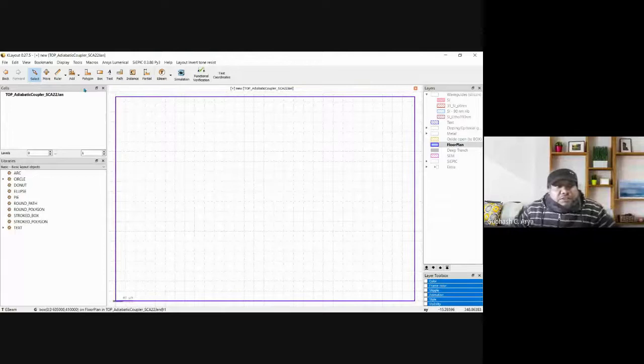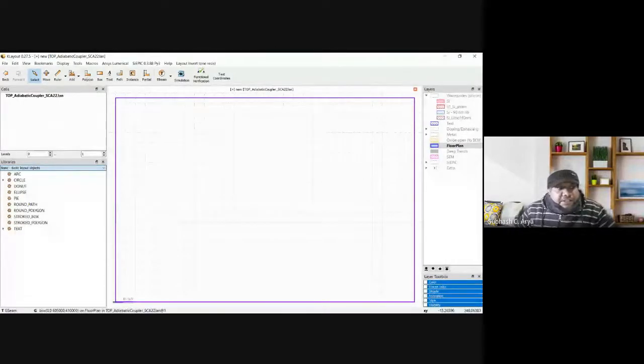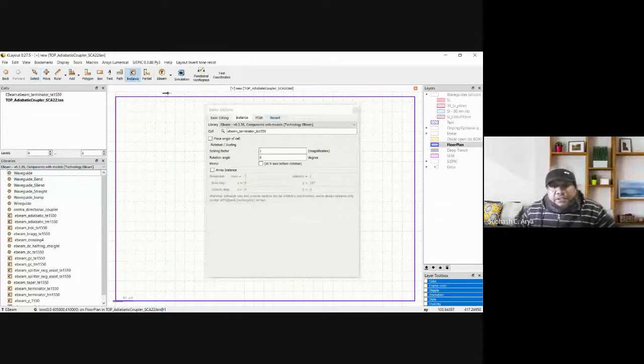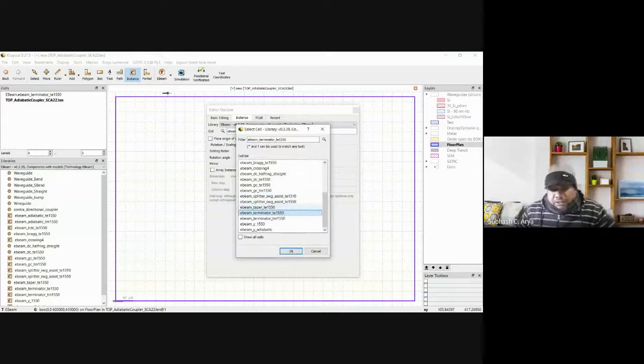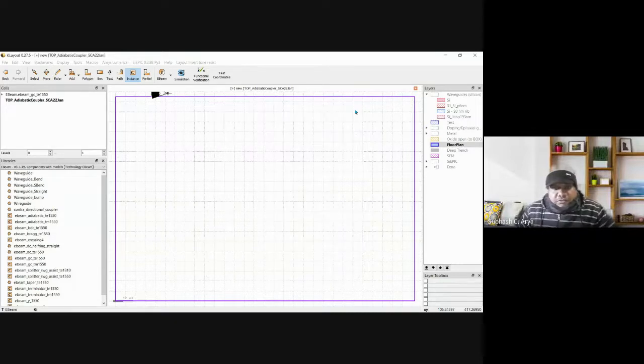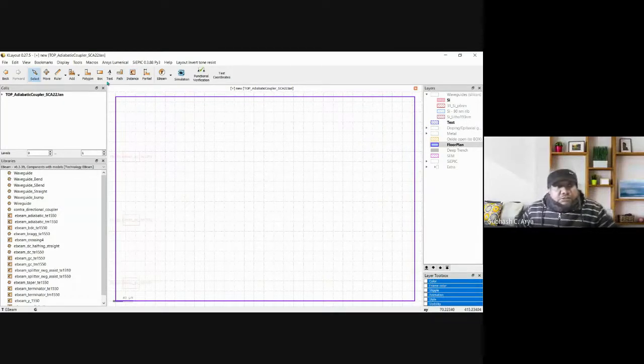Now, as usual, we have to select this library, EBeam v0.3.39, and after that, registers. From here we are going to select this grating coupler to couple the light, because it is essential. So this is a grating coupler. I will select three arrays here and go to this side. Press escape. Since it is not visible, go to full hierarchy.